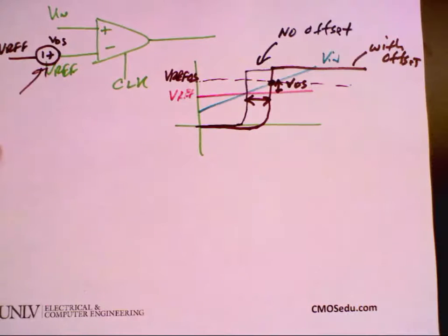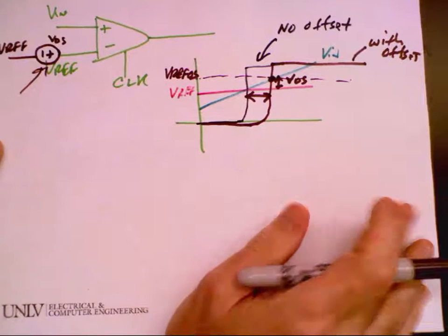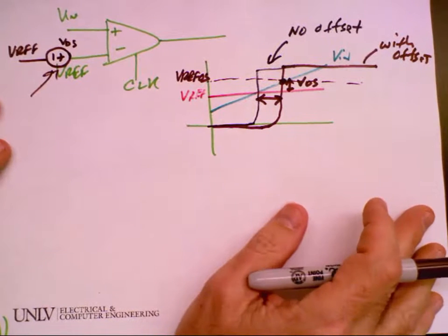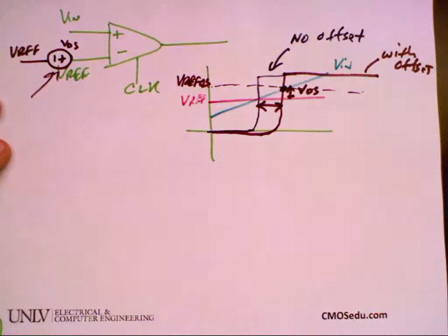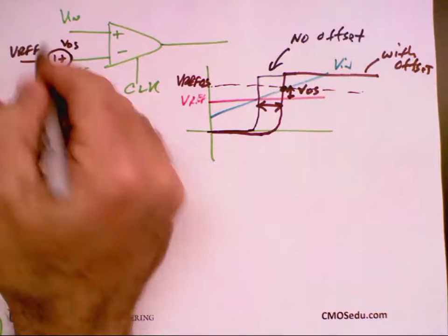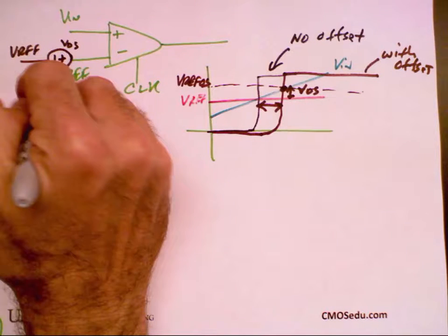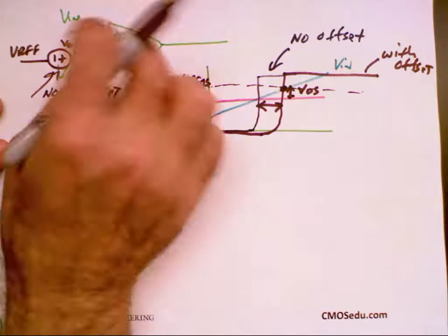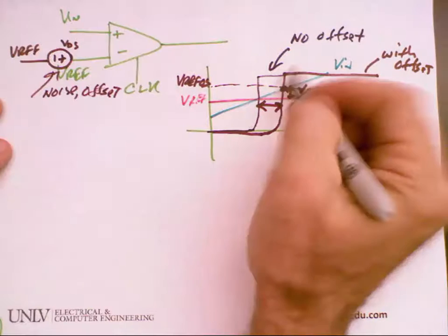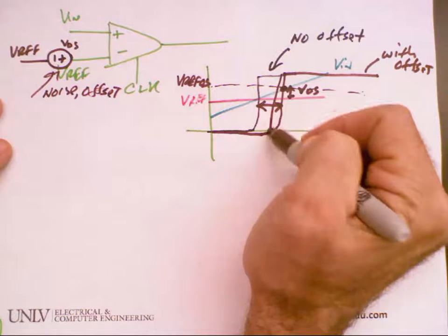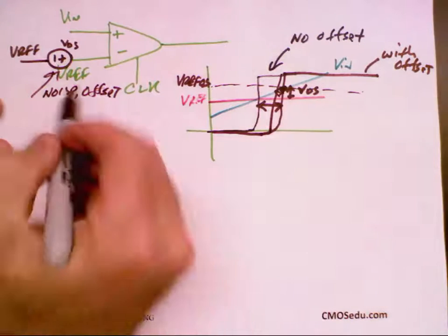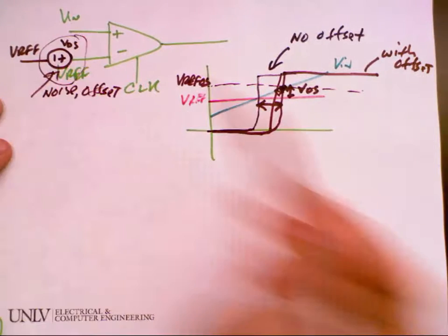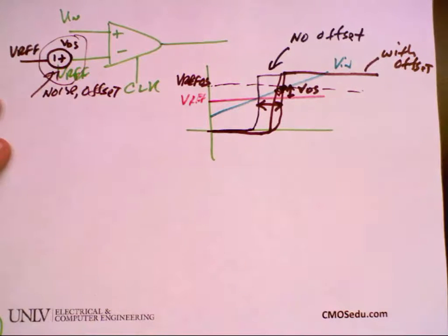Then I ask, how does that influence the behavior of my modulator? Let me also point out that when I do noise, I model it the exact same way. If there's a little bit of hysteresis, instead of it always switching right here, when I go the other way it switches right here, I model it as an imperfection on the input of the op amp, or comparator. Does everybody follow that?